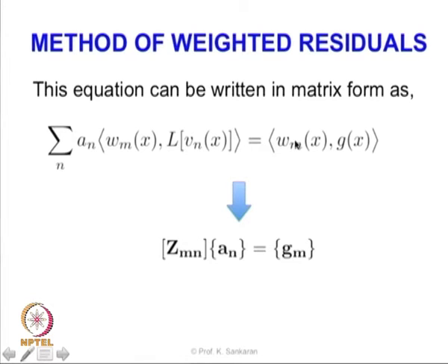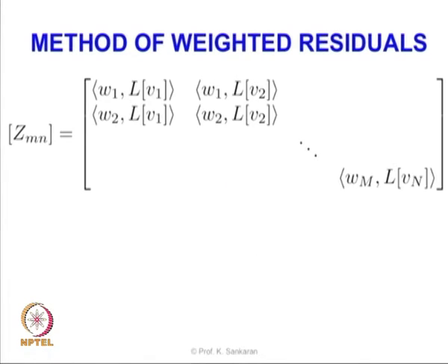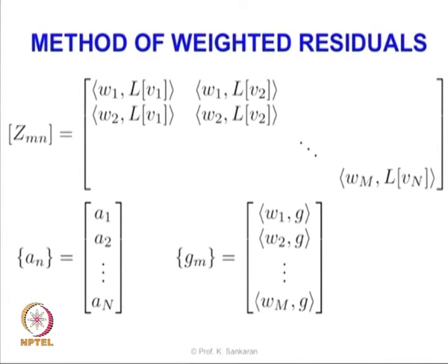So when we are expanding this, we will see the terms as follows. This is the starting point where we say the method of weighted residuals is: we are weighing it with respect to a test function, and we are doing the testing on both sides. How are we going to go from this point to the Galerkin method? It is a very simple assumption.